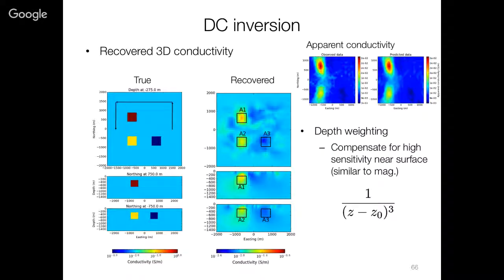So what's generally done, you do the DC resistivity inversion. So you take the DC data and you go ahead and you invert them. An important thing here is that it's just gradient data, so you've got only one transmitter. That doesn't give you depth of penetration, particularly. It's kind of like a mag survey or a gravity survey.